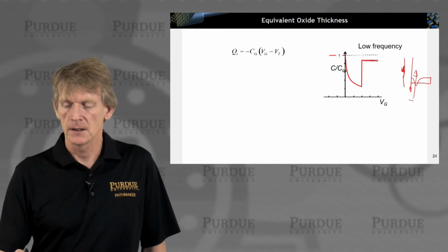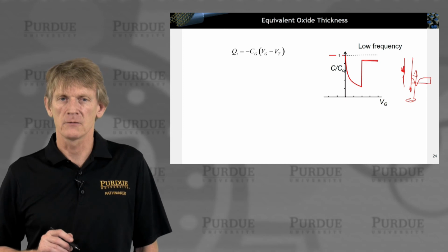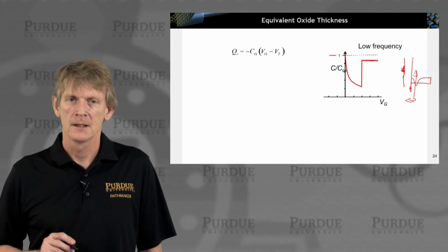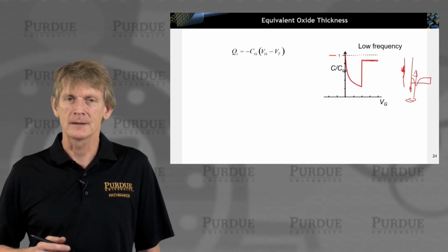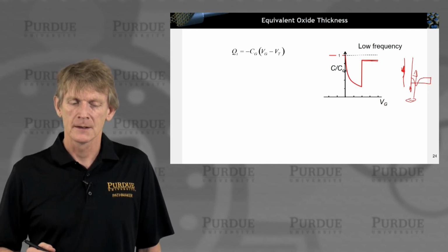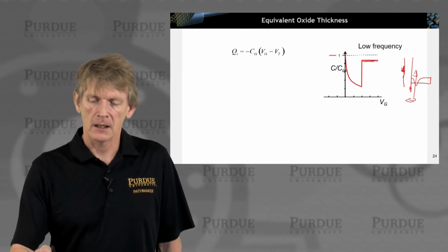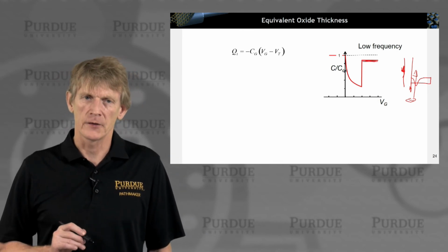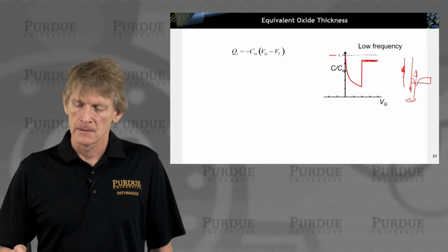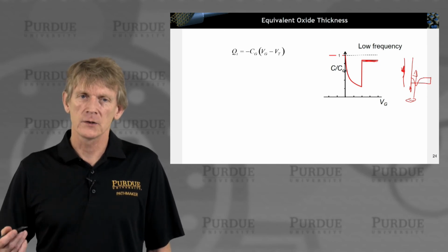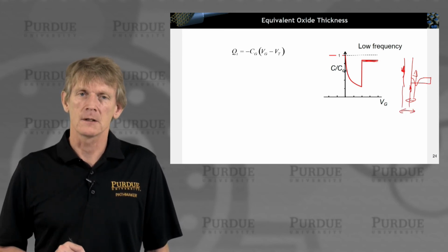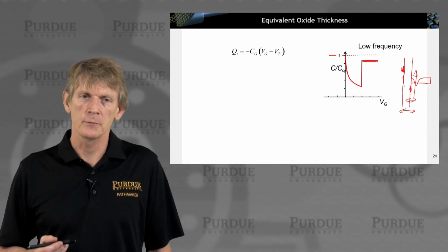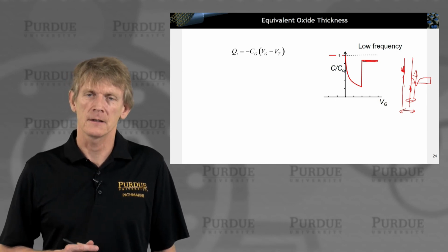So there is a separation of, say, a delta function representation of the total charge. If you calculated the first moment of that distribution, you will find it's not at zero. It has a certain width. Therefore, it can't climb up far enough. That means for the capacitive response of the system, you can think of this as having made your oxide a little bit thicker. Electrically speaking, you made your oxide a little bit thicker.